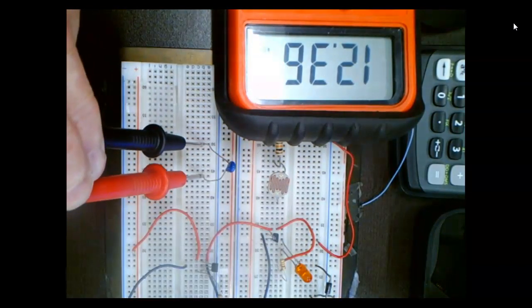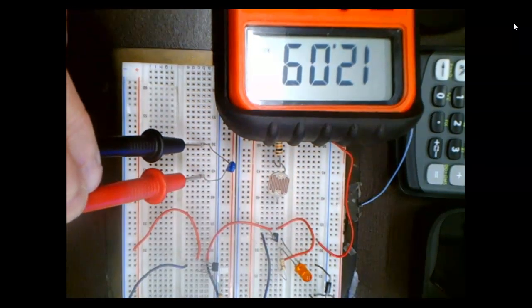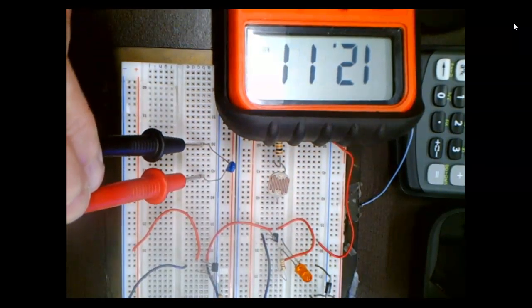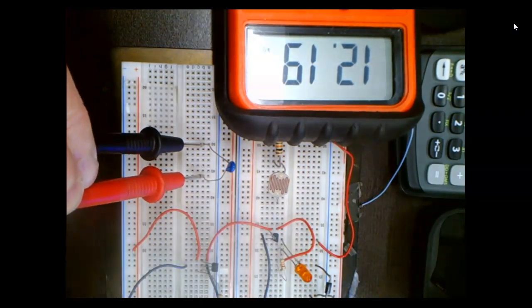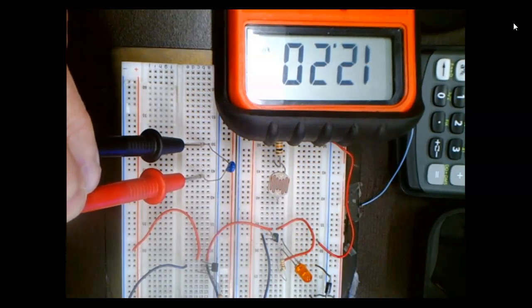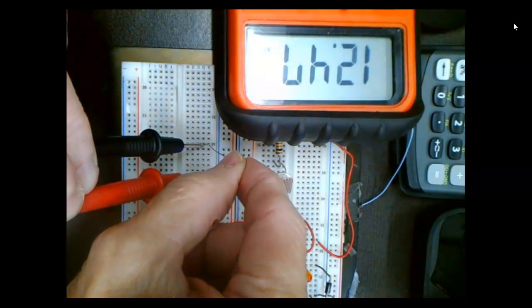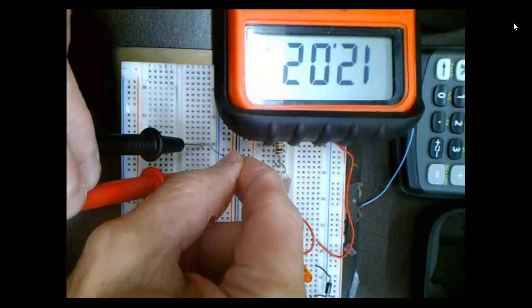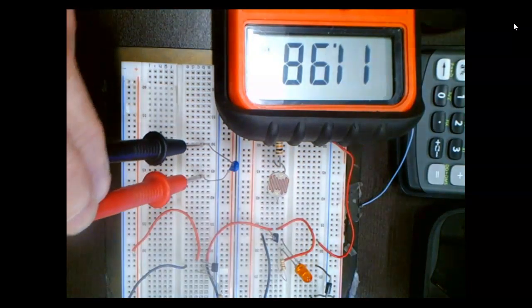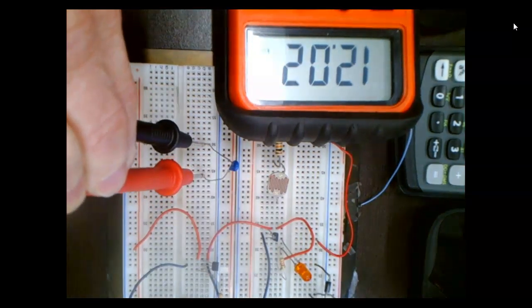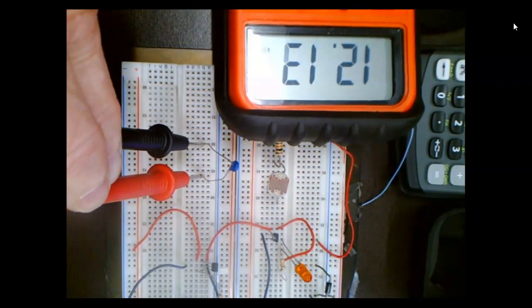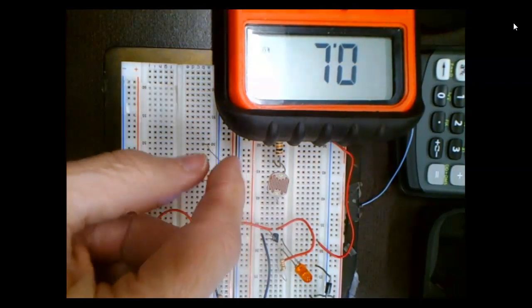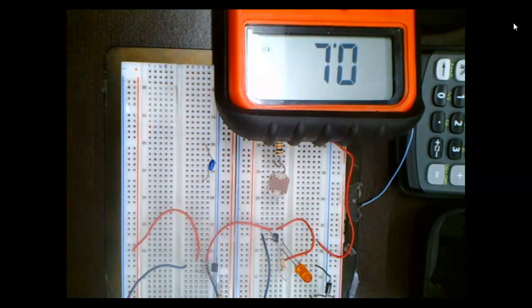So this is probably what they use in these little electronic thermometers that you put in your mouth, right? But no, there they probably use a PTC, right? Because when your temperature goes up, you want okay, well, that's not true. We'll see how we do this. But I want to take this. It's real hard to transmit a resistance. So what I need to do is take this change in resistance and convert it into a voltage. How do I do that?